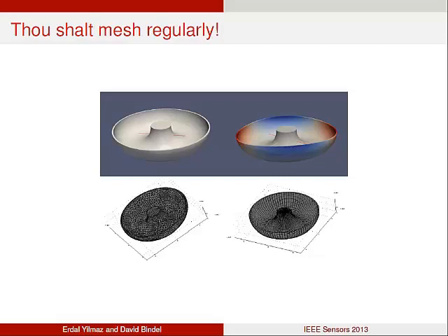So here I show a simulation of a resonator called a birdbath resonator. A birdbath resonator is like a toroidal shell cut in half. Here I have simulated it with COMSOL. After just drawing the geometry, I pressed the automation feature of COMSOL, and as a result, we get a mesh which contains triangular pyramids.